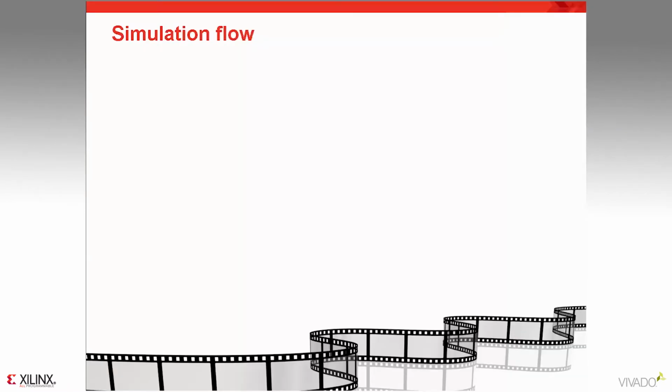The simulation flow uses a three-step process: compile, elaborate, and simulate. vlog or vcom for compile, vopt for elaborate, and vsim to simulate. Vivado creates separate scripts for each flow so that users can take the compile and/or elaborate script to their custom environment.